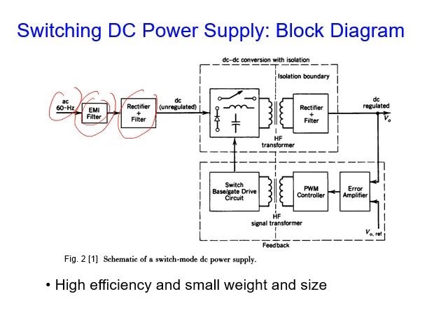Now we didn't use an isolation transformer yet. The output is an unregulated filter, usually we use a capacitor, as we explained in the rectifier circuits. And here you can see I have inductance, capacitance, switch, diode. We can construct them in a way to give either a DC-DC converter or an inverter, okay, half bridge, full bridge, push-pull.